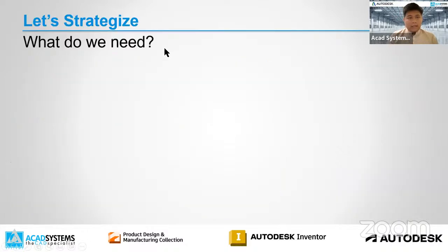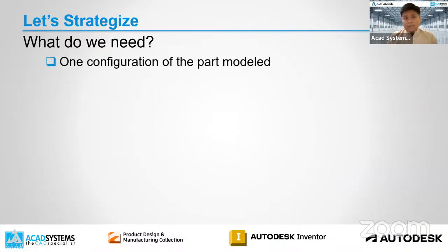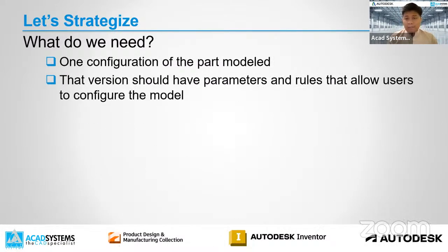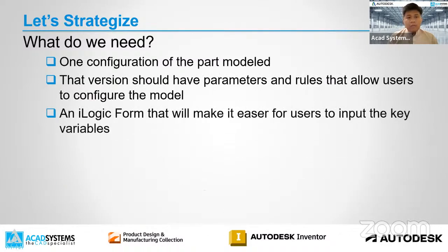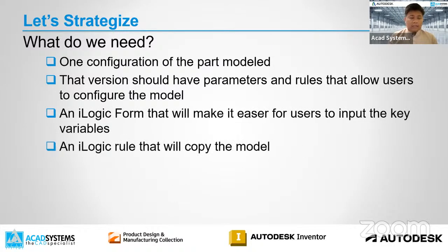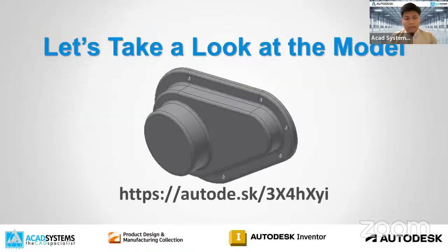So let's understand the strategy first. First thing, we need to configure the part. The second, we need to set up the parameters and rules. The third, we need to create the iLogic itself. And then we just run the iLogic on the model.